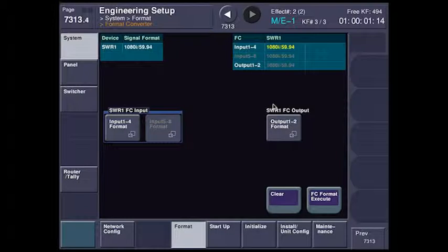Now, frame delay mode can be anywhere from 1 to 8 frames of delay. At 1 frame delay, it's a frame sync. I can put non-synchronous sources into the switcher. From 1 to 8, though, I can dial up and use maybe something like a virtual set system, which might have a few frames of delay, and I want to make the input converter follow that much delay. We're going to set this back to 480i and leave it where it was.